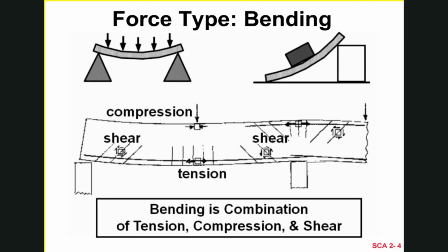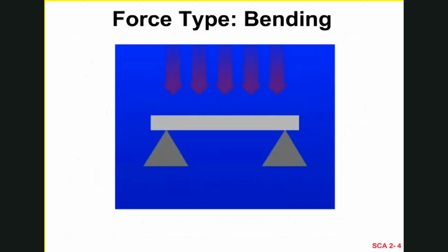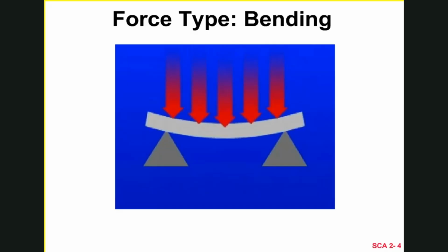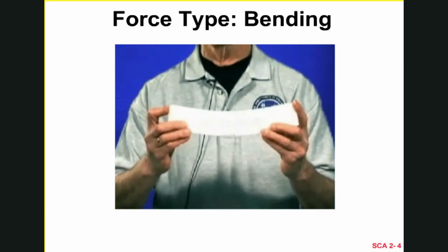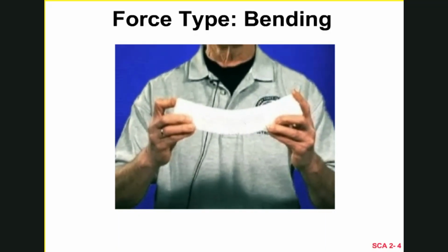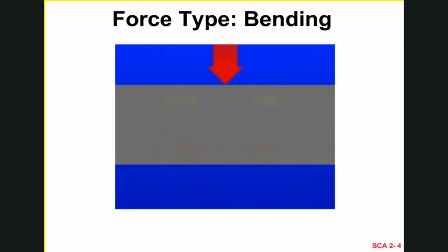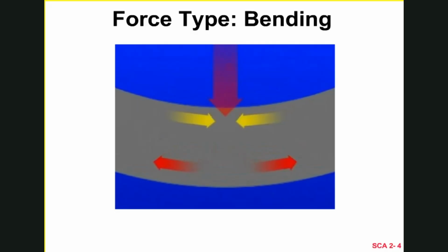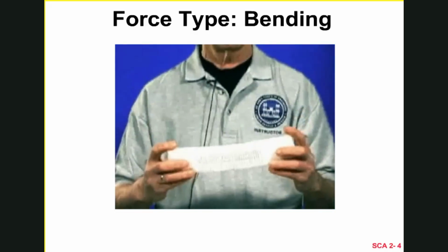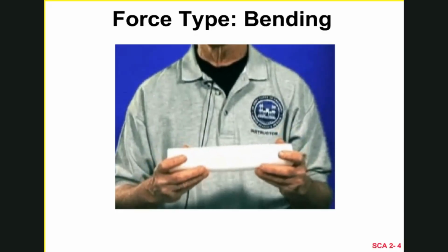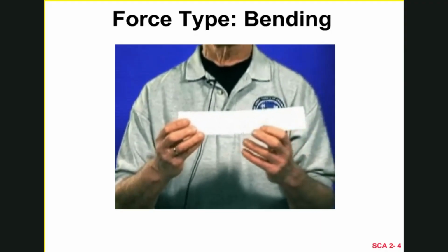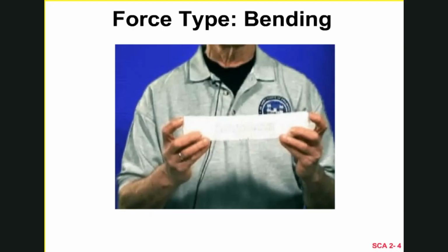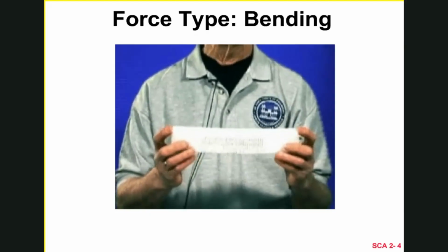Third concept is that of bending. Anyone that stands on any floor, like the floor I'm standing on, the members underneath them are bending, and what happens in bending is that the bottom of the beams or slabs will extend and get in tension, and the top will shorten and be in compression. And that's important to us when we look at concrete structures, because in concrete structures there's reinforcing steel placed where the tension will occur, because concrete is very weak in tension, and we add the structural steel or the rebar to it, which takes that tension.